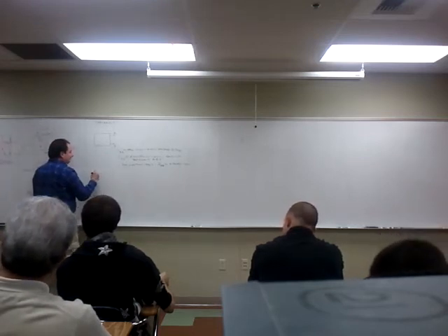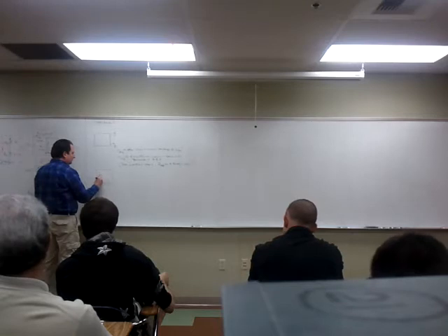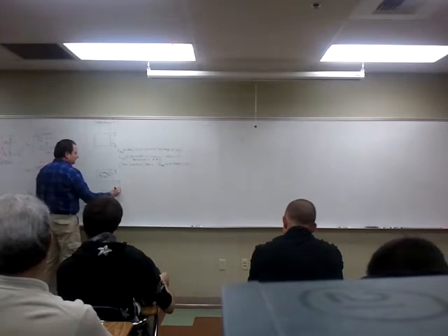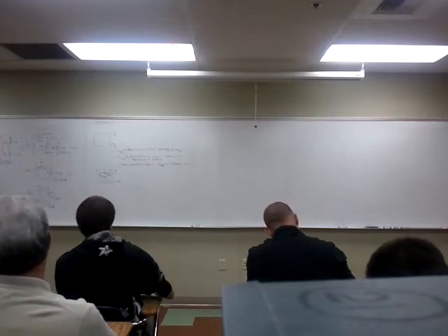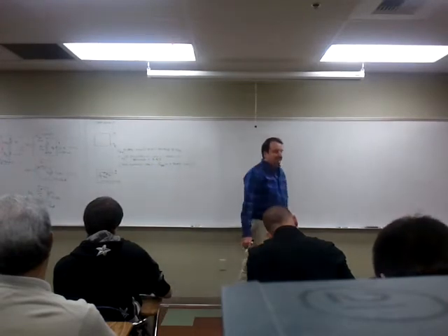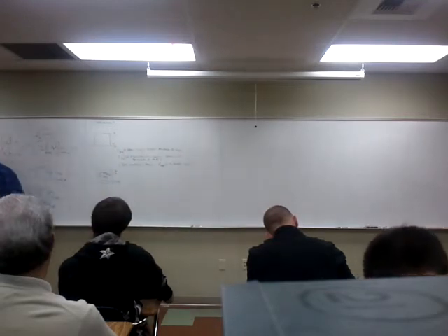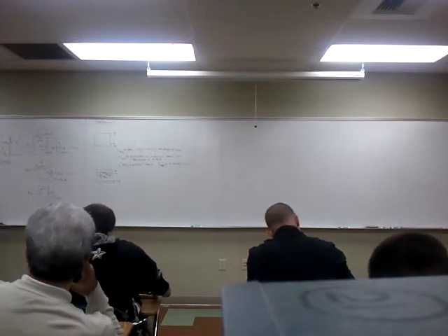Well, if you can do that, what can be in this box is an equivalent circuit that consists of the Thevenin voltage and a series resistor that you call R Thevenin, and it comes out to terminals A and B. That is the Thevenin equivalent circuit. And the idea of this is to take a complex circuit and convert it to this simple circuit.